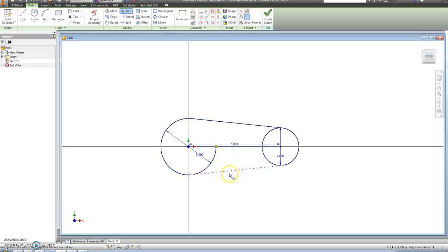So we're going to left click on that, left click on that. So now all we have is the outside arc. Left click, and it could have cut all that off prior. I'm going to hit escape real quick. If I had deleted this line first, it would have trimmed off the whole arc instead of 2 segments. It was intersecting that piece of geometry, that line, originally. Okay, so now I have the footprint of my shape.